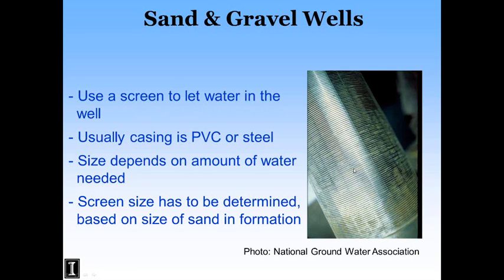And if you have a sand and gravel well and you're pumping sand, it either means that there's some kind of breach in the screen, or whenever you install this well, let's say this is a 6-inch casing, you may drill a 12-inch hole and you put gravel pack around that screen, which is larger particles, so that it'll help keep the fines out, and there may be a problem with your gravel pack having a breach in it.